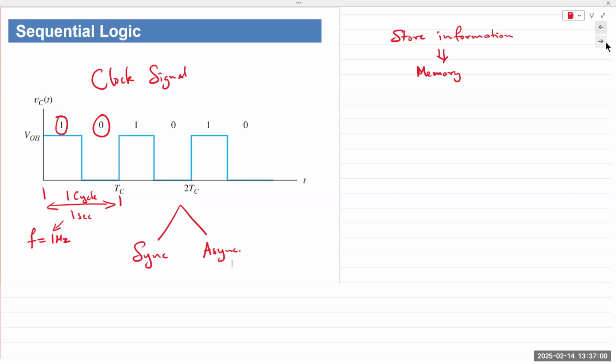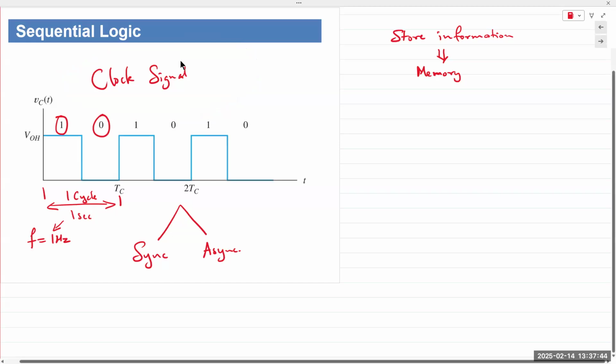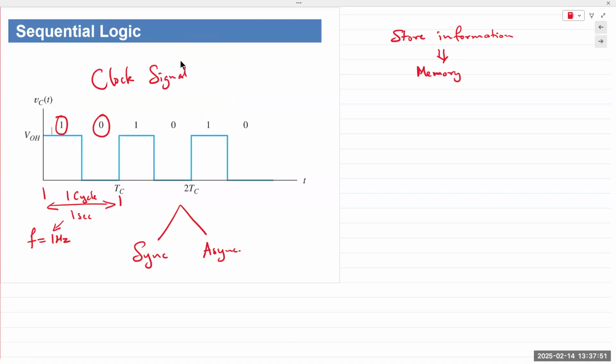As a real life example, think about the CPUs in your mobile phones, tablets, desktops, and laptops. The frequency of those CPUs is 1 gigahertz, 2 gigahertz, 3 gigahertz, and probably even larger than that. That frequency is the frequency of the clock signal that is running your entire system. It's keeping everything in sync. Every time a process occurs, it occurs in a sequence and that fast. So if a cell phone says a CPU of 2 gigahertz processing frequency, that's the clock signal frequency that's running things. It's performing that many operations in 1 second.